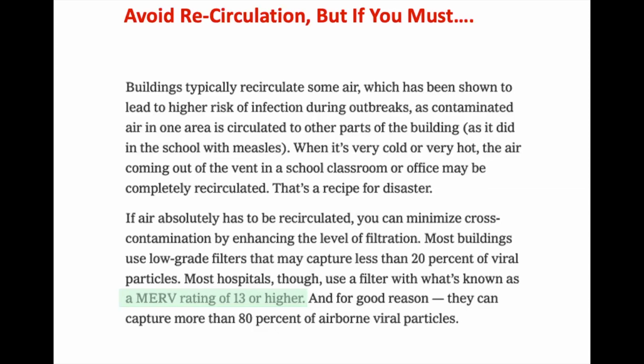The other conversation we have when I've sat in on these workshops and presentations is that it's, well, you know, we can do this, but it's going to be a huge energy penalty and it's going to cost a lot to do that. And it's right, because when you do put on a MERV 13 filter where you used to have a 6, your fans are going to use 2 or 3 times as much power. And you open it up and you're bringing in all that outside air, you're going to have to cool or heat and dehumidify that air 100%, and it's going to have a huge penalty.